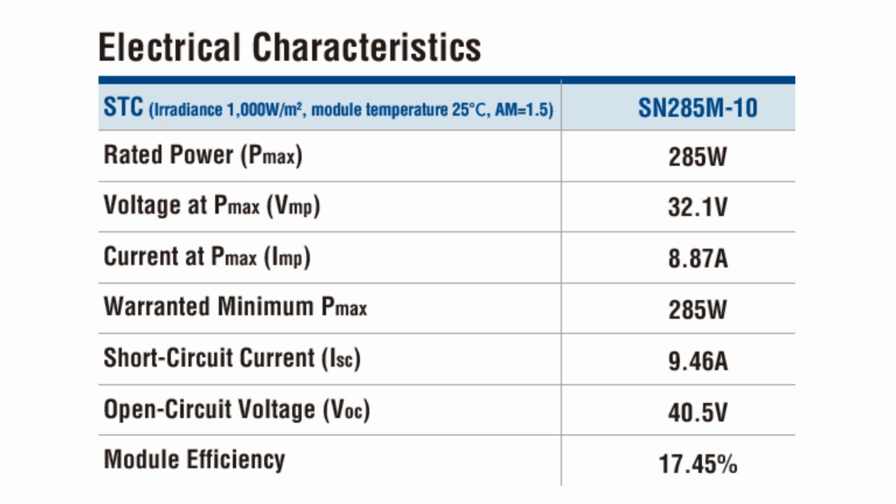When you do all your sizing calculations for National Electric Code, you're using the short circuit current and the open circuit voltage. When you size based off the short circuit current, that's your current that will not be exceeded for the solar array.